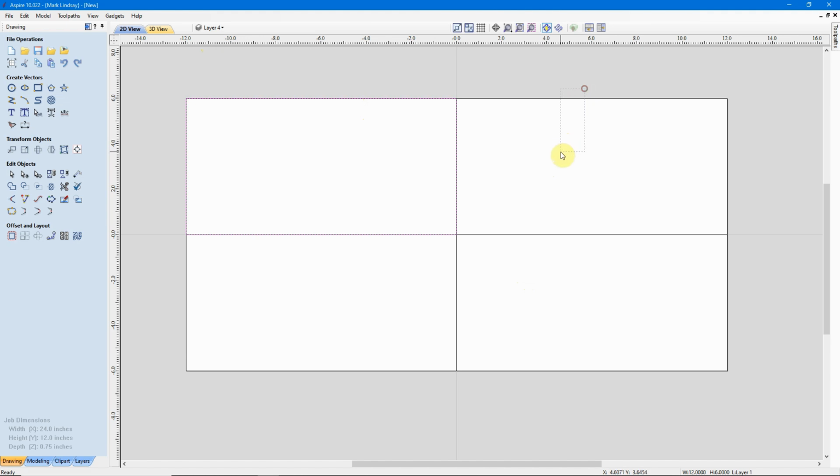I have a rectangle here, here, here, and here. One of the reasons for placing them on separate layers is if I should need to select this rectangle, if I select this, I've selected both of these. If I just want to select this rectangle, sure, I could come out here and select this rectangle only. But if I want to eliminate confusion, I will just turn off the other layers, make sure this is my active layer, and go to work there.